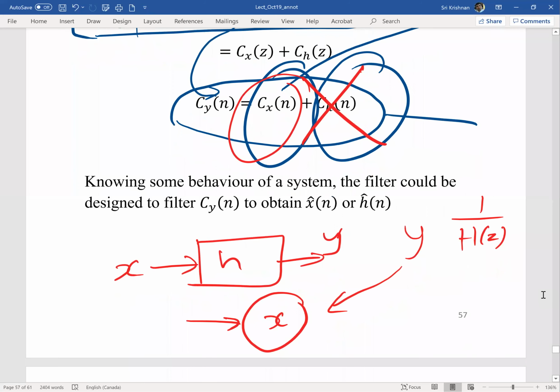And you will get to appreciate this more as we go along, in many cases when we are operating on Y, it happens to be a distorted version of X or amplified version of X or other modifications on X. So to know what those modifications are, the deconvolution process or the inverse filtering process comes in quite handy.